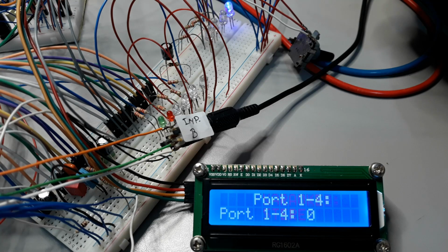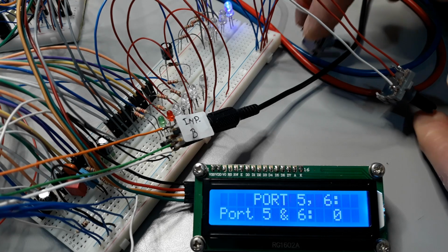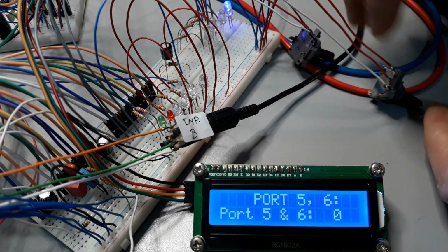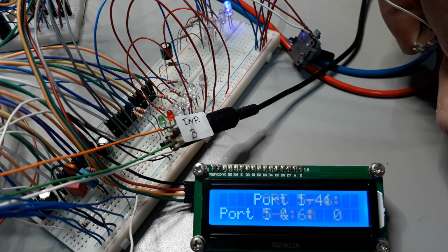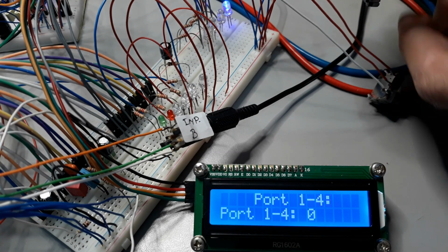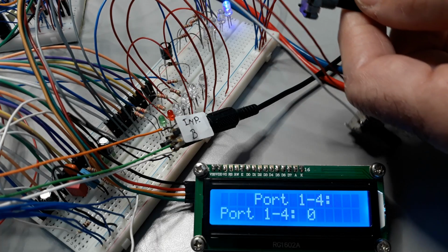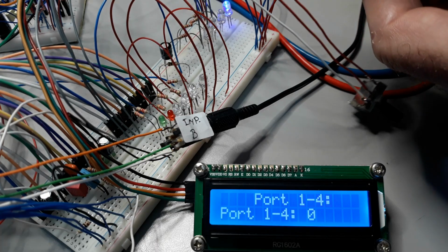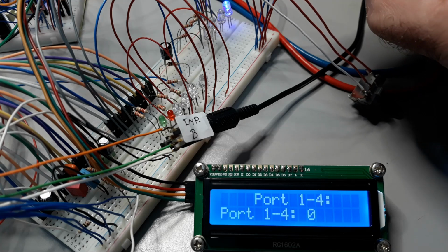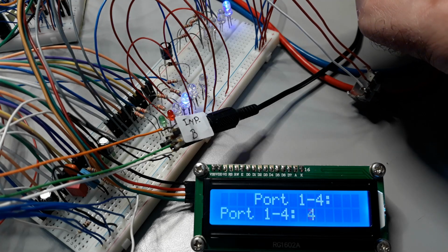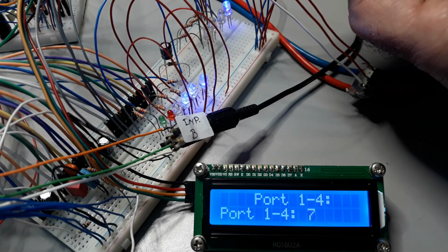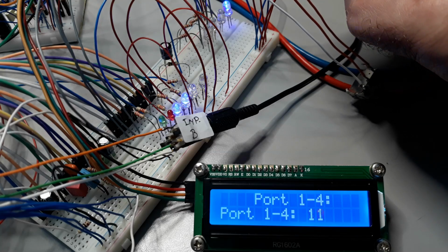It would have been possible to use a 32-bit variable to hold all 18 bits at once. However, because the protocol mixes fields of 4 bits, 3 bits, 2 bits, and even single-bit values, that approach becomes harder to read and harder to understand. Using a 16-bit variable turned out to be a simpler and clearer solution.